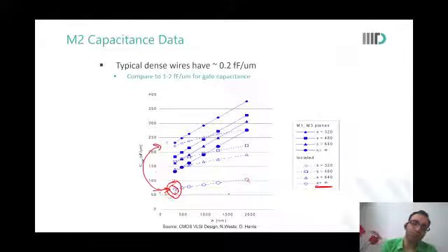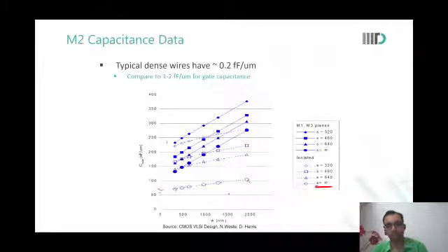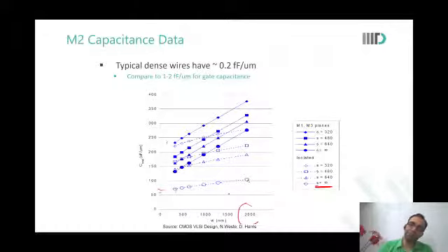Are you able to see this? Okay, so it means that when we're going to very small dimensions, the intermetal one is getting neglected. Intrametal capacitance dominates. In between the same layer, it is dominating, but between layers is now okay. Yes, and if you were using wide wires, then intrametal also has some influence. See what happened?